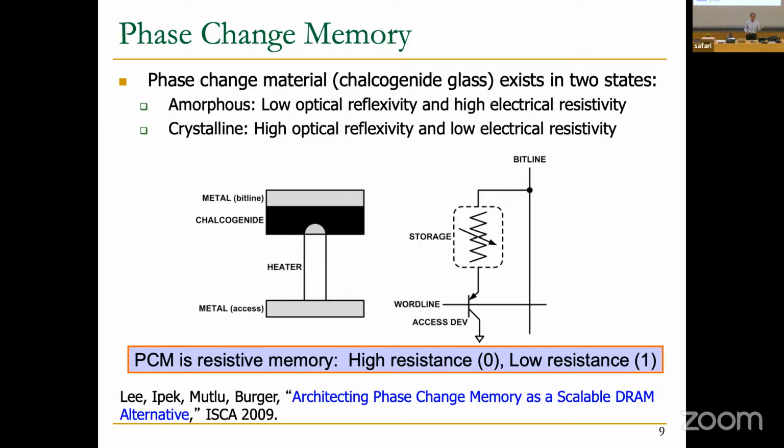So these two states represent 1 or 0, right? So this is how you can represent things. This is another analog representation potentially, right? But the reading mechanism is optical. So more recently, people have developed a lot of reading mechanisms that enable us to detect the current out of this, essentially detect the resistance that's stored over there based on the current that's flowing. And as a result, people have manufactured these in the form factor and with reading mechanisms that are compatible with what we use for main memory.